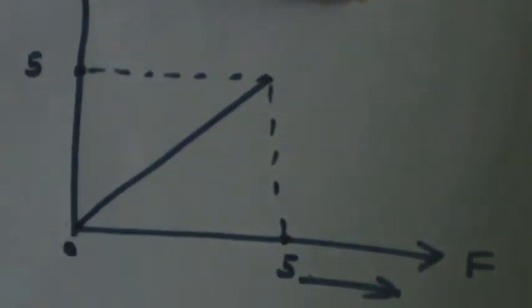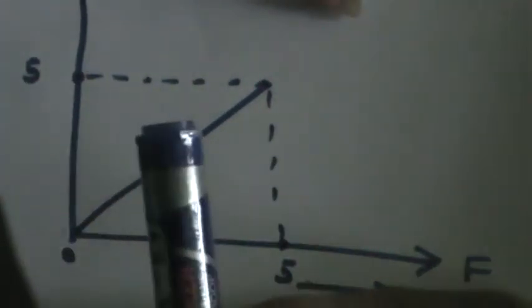But beyond that, if you increase this force even by a decimal point or some fraction, this force will change, but this force won't change. So this is the maximum y value that this force can take. This is actually the moment at which the object starts to move.